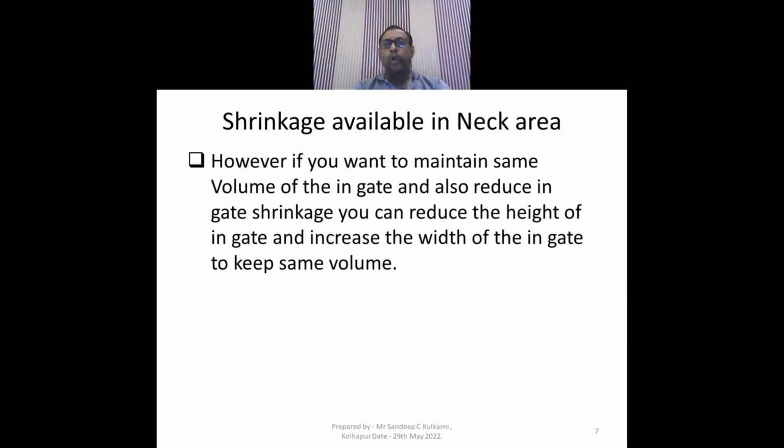However, if you want to maintain the same volume of the ingot and also reduce ingot shrinkage, so that your feeding will be proper, then you can reduce the height of the ingot and increase the width of the ingot to keep the same volume. The volume remains the same and you will get enough feeding, but you will reduce the ingot shrinkage by reducing the height of the ingot. So this is for shrinkage available in neck area.